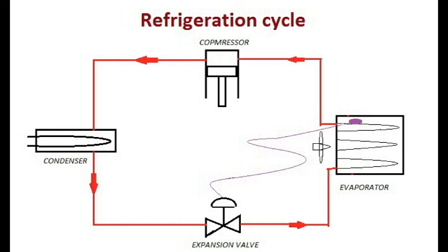When vapor is compressed, it rises in temperature. Therefore, the compressor transforms the vapor from a low temperature vapor to a high temperature vapor, in turn increasing the pressure. This high temperature, high pressure vapor is pumped from the compressor to the condenser, where it is cooled by the surrounding air, or in some cases by fan assistance. The vapor within the condenser is cooled only to the point where it becomes a liquid once more. The heat which has been absorbed is then conducted to the outside air.